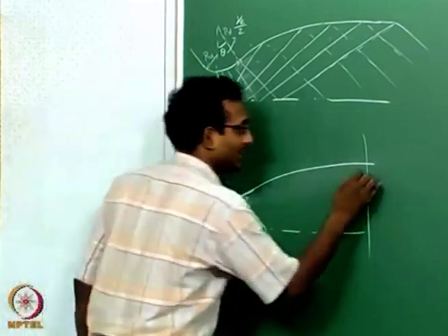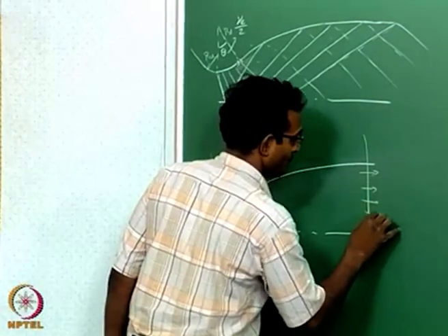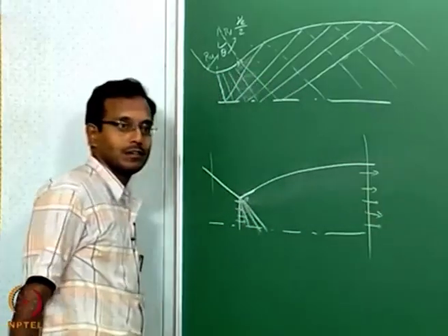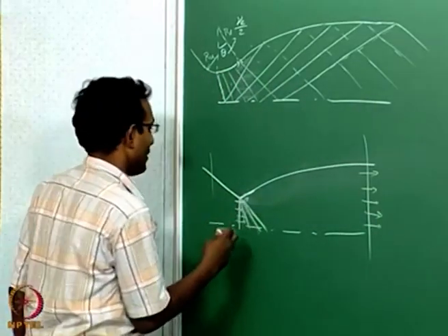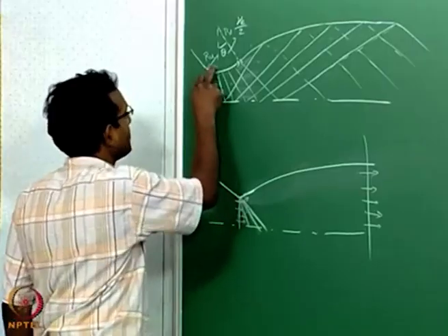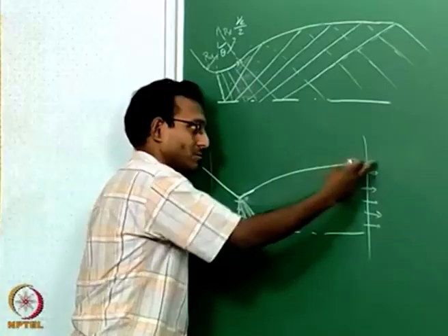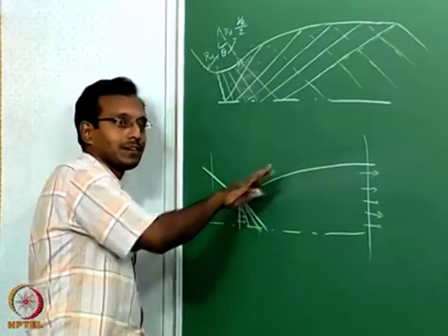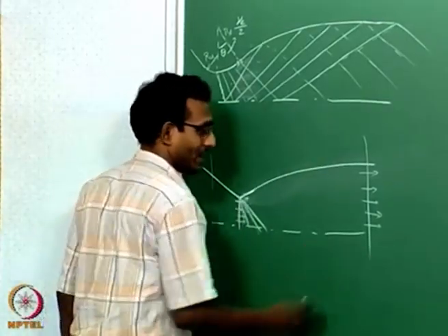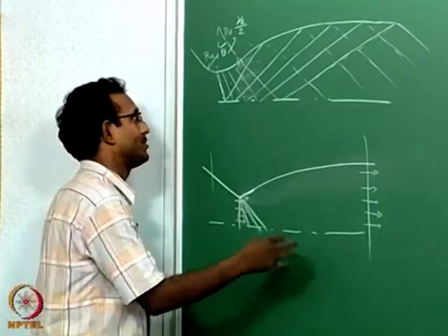That is assuming I still want uniform Mach number and uniform theta being equal to 0 everywhere. If that is the condition, if I have R downstream, R upstream equal to 0, then I will get only compression, no expansion part. That is the minimum length you can ever get in the nozzle. This is your minimum length nozzle.